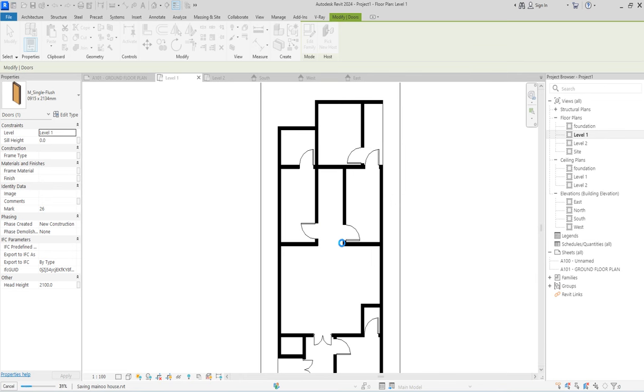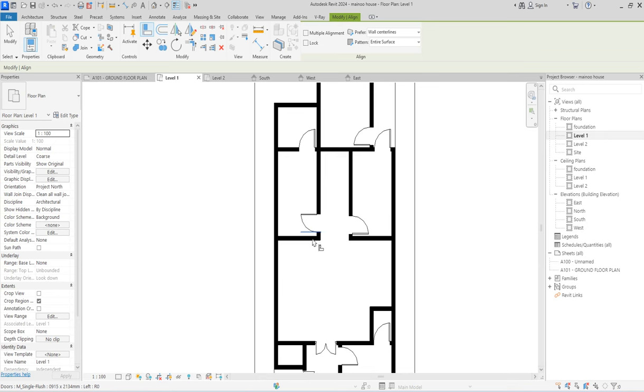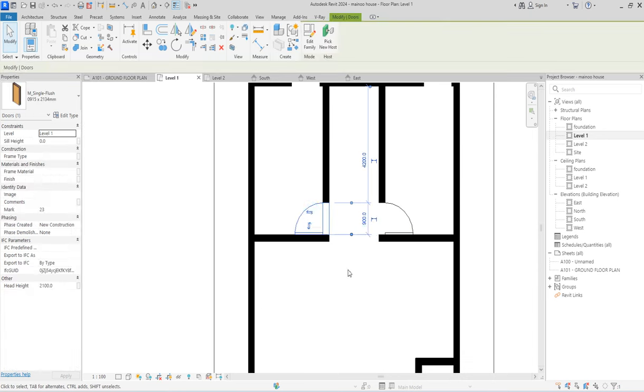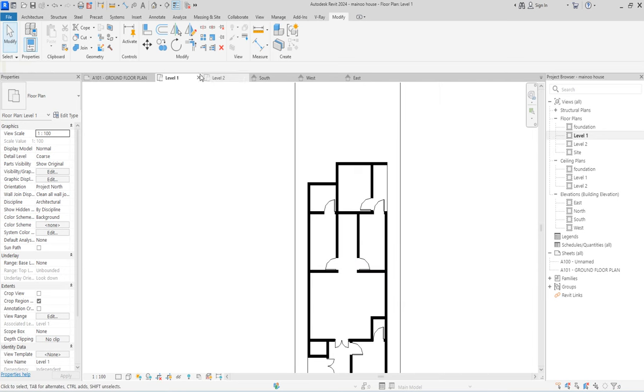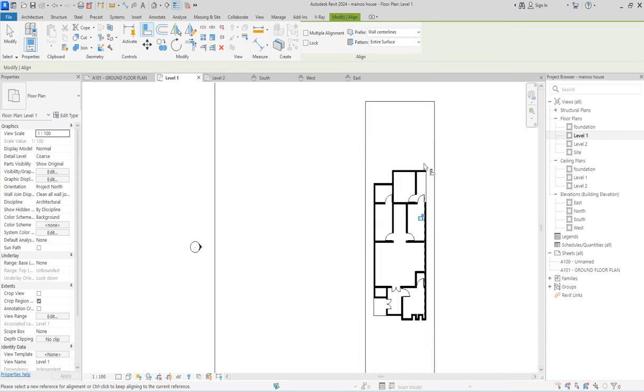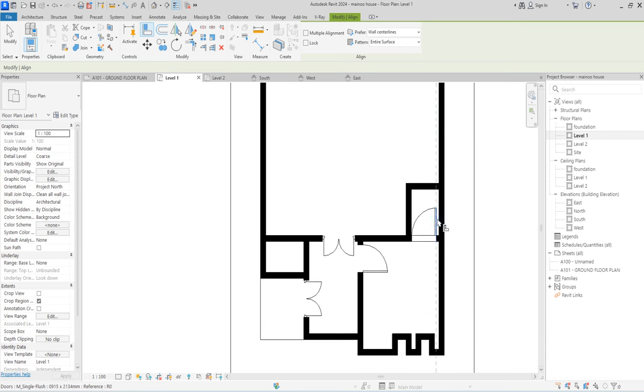So when you have this in place now, you can continue to work on various aspects. When we have all the openings, which are the doors, you align them to the wall. So change, flip the way it opens. Align everything to wall. Then you can see the way it flows, and flip it again.